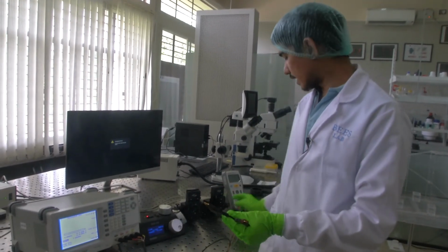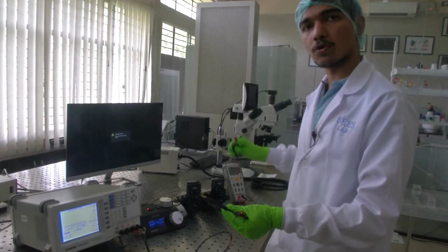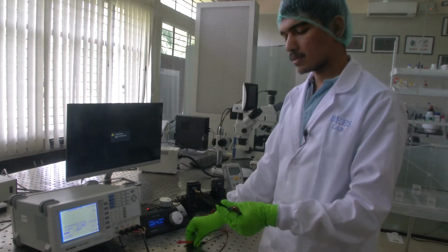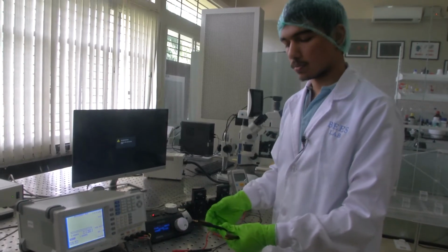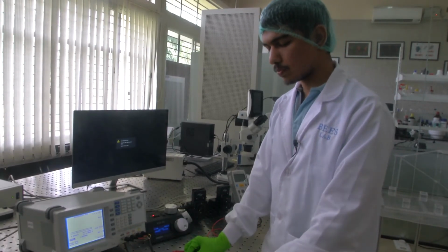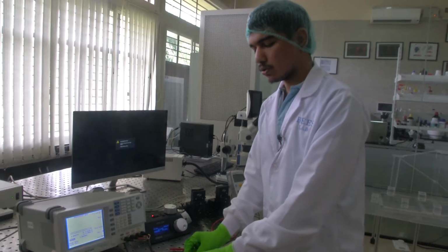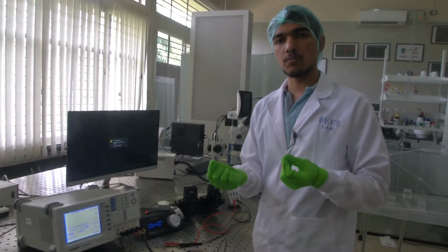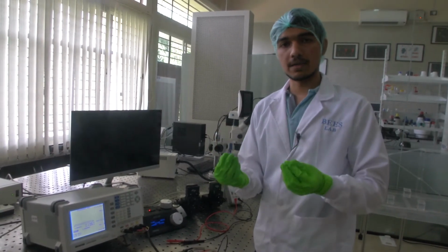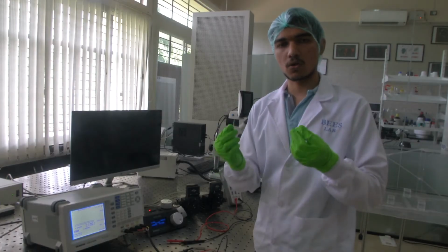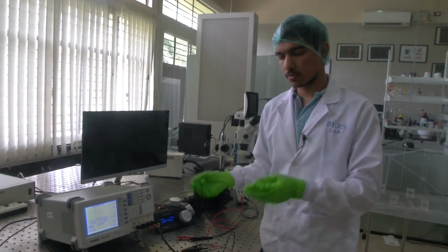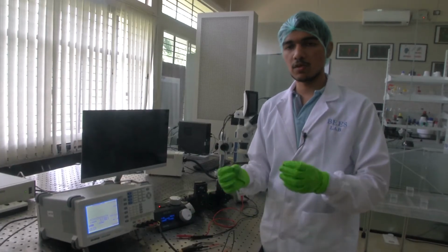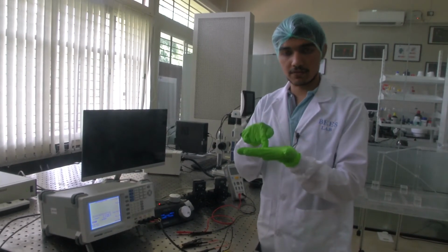You can see here in the LCR meter, there are only 2 probes like an ammeter or a voltmeter. So, what is essentially the difference between a 4 probe and a 2 probe instrument? You know that when we measure the impedance of a sensor that we have fabricated using these probes, we will be contacting it to the surface, right.